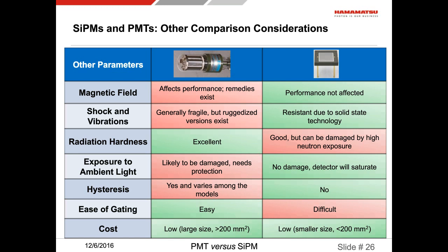The cost for PMTs, well, it can be high or quite low. It depends. If I request a PMT that has 1 millimeter by 1 millimeter size, that will be very expensive because it's very difficult. PMTs are still, or some aspects of PMT are handmade. And so making such a tiny PMT could be quite expensive.